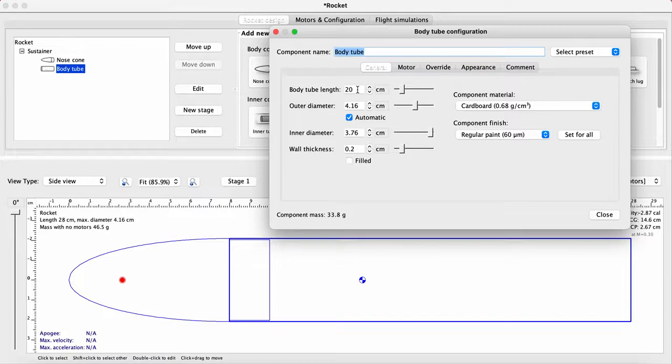First question is, how long is it going to be? Well, your lab kits come with two 18-inch long tubes and a coupler. So in other words, there's a little tube that you'll notice can bind the two body tubes together for a total of a possible 36 inches. All right. Now, it doesn't have to be that long. If you use the full length, a long rocket is kind of impressive looking. Shorter rockets, however, have less mass and will go a little bit higher. So it's all about you to decide.